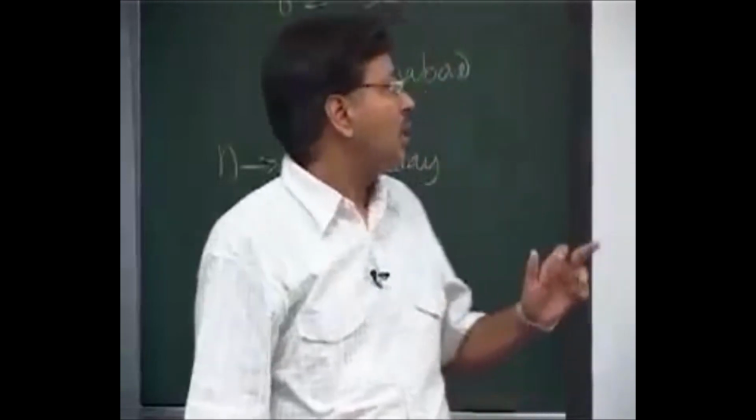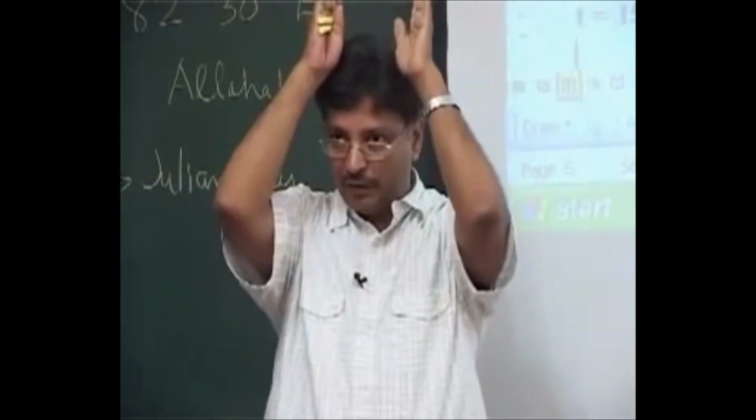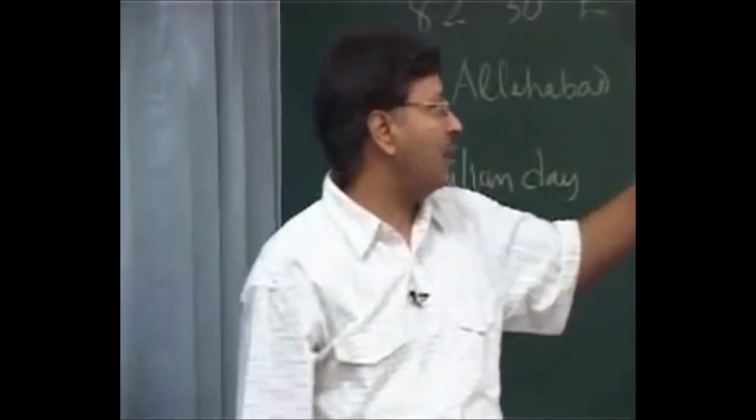So where do D and T come from? T is the hour angle. Hour angle is between you and the sun, on the cycle. Hour angle changes by 15 degrees every hour. So you see here the apparent time, which is corrected; see the difference with respect to 12 o'clock. If the sun was right on your head at 12, this will be 0.